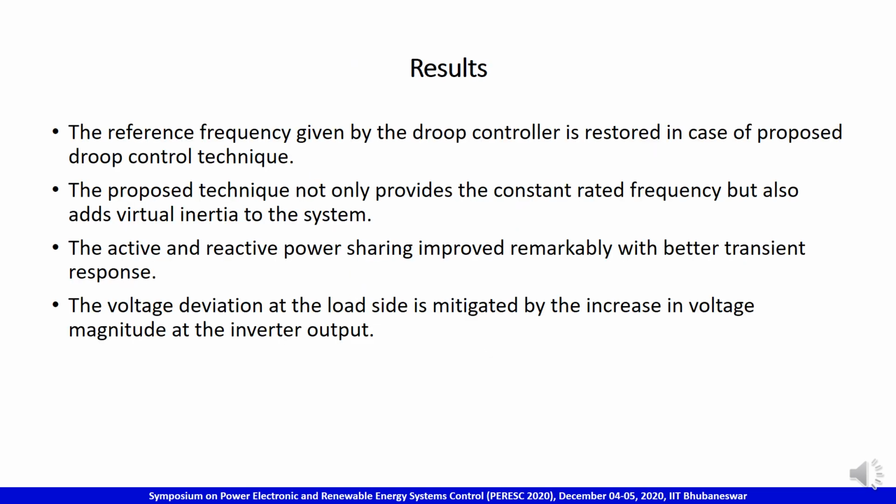Simulation results show the restoration of the rated frequency of both inverters and improved reactive power sharing between the DG inverters by properly selecting the control parameters. The proposed Droop control, unlike the conventional Droop control, improves the transient response and provides virtual inertia during various contingencies.